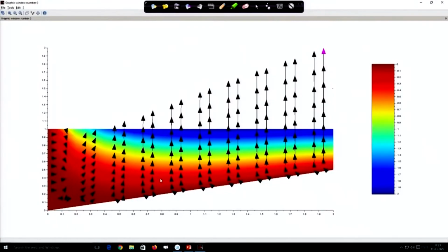Temperature is a scalar, but flux is direction dependent because we have an x component and a y component. What boundary conditions had we given? On this line our flux was prescribed as 15, and that was normal to this boundary. The normal to the boundary in this case is in the y direction.